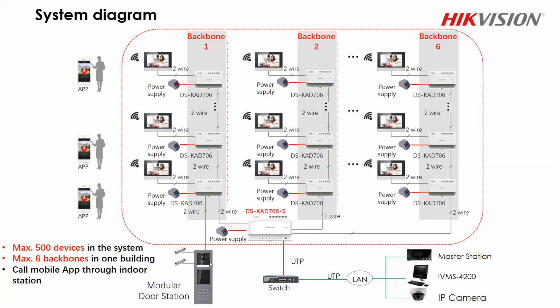If someone breaks this, then the door will be open for them. If you want to make the system more secure, we recommend adding in a secure module in between. The secure module is installed on the safe side of the door, separately powered, and the locks are connected to the secure module directly. In that case, if someone breaks the door station, the secure module will still keep the door locked.